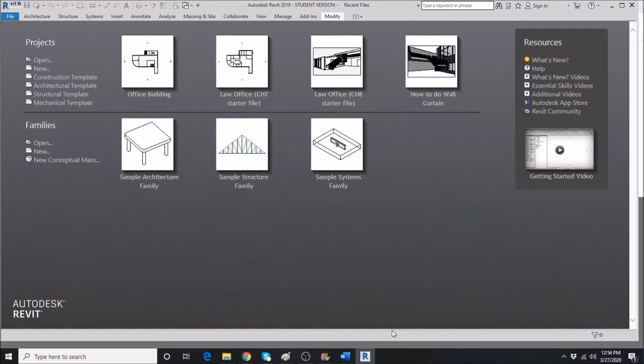We are going to integrate the structural system into our architectural plans. To do this, there must be two Revit project files open. One is the source of the structural system, and the other is your file for your project. So go ahead and launch your Revit, whatever version that could be. Again, there's nothing open. I want you to directly open first your Revit 2018, 19, or 20.